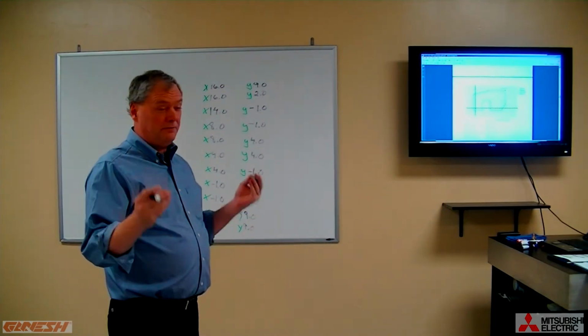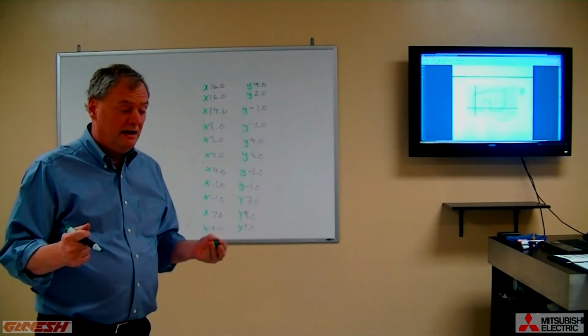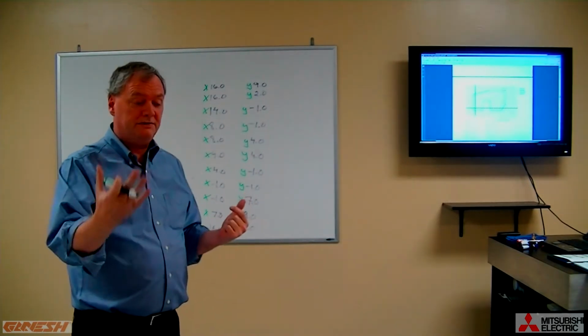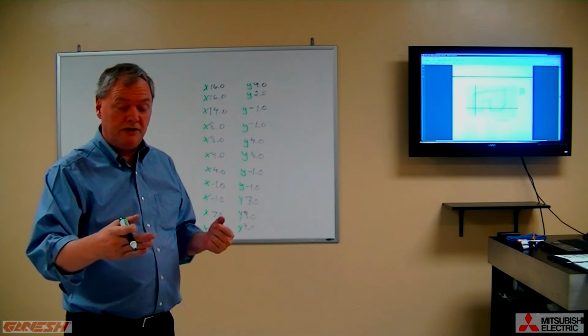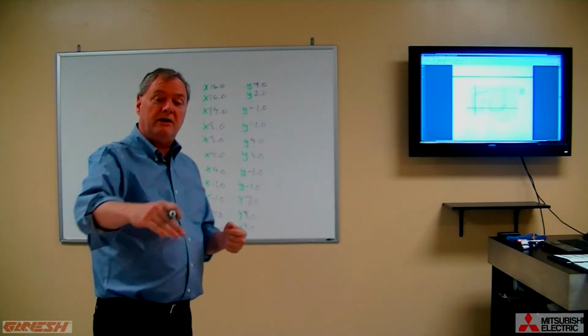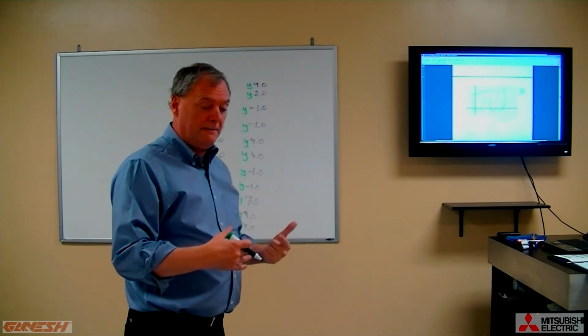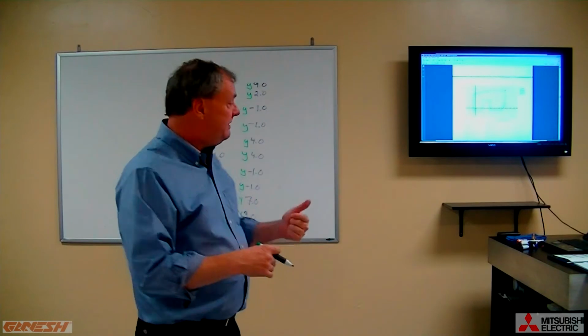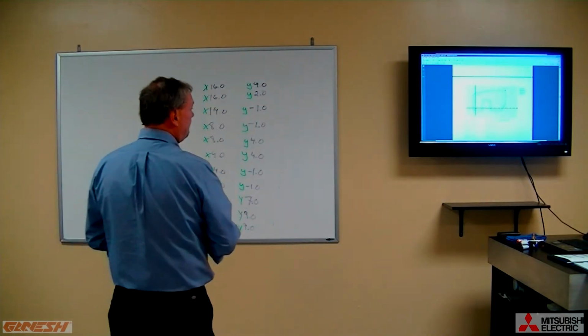So all an NC program really is, is a way of doing these things. Turn on spindle, specify an RPM, turn on coolant, bring your cutter down, and let it start making a part program or part profile based on the coordinates you provided.